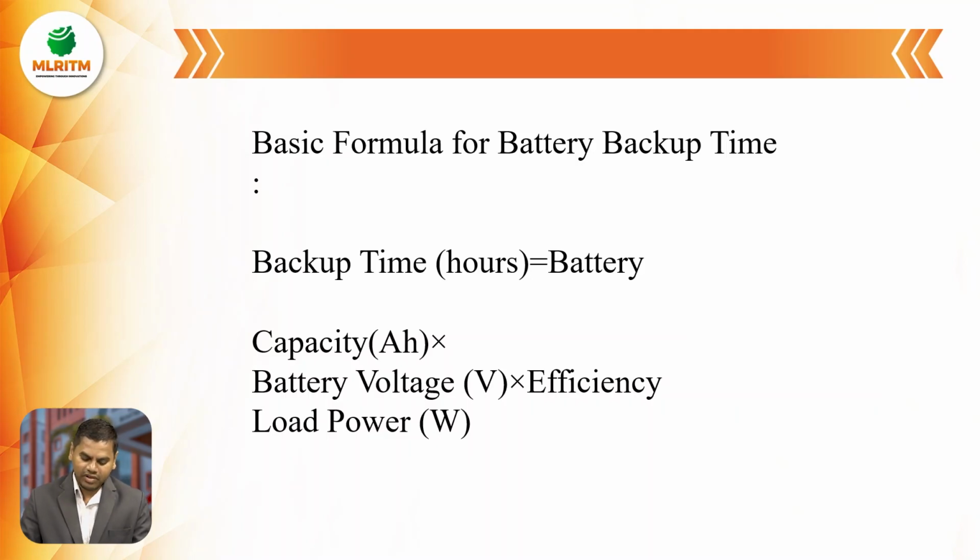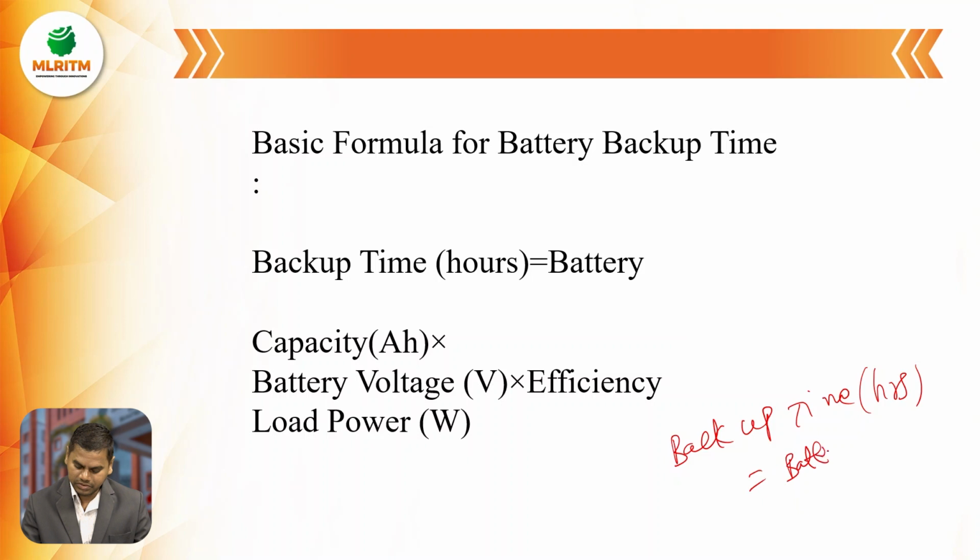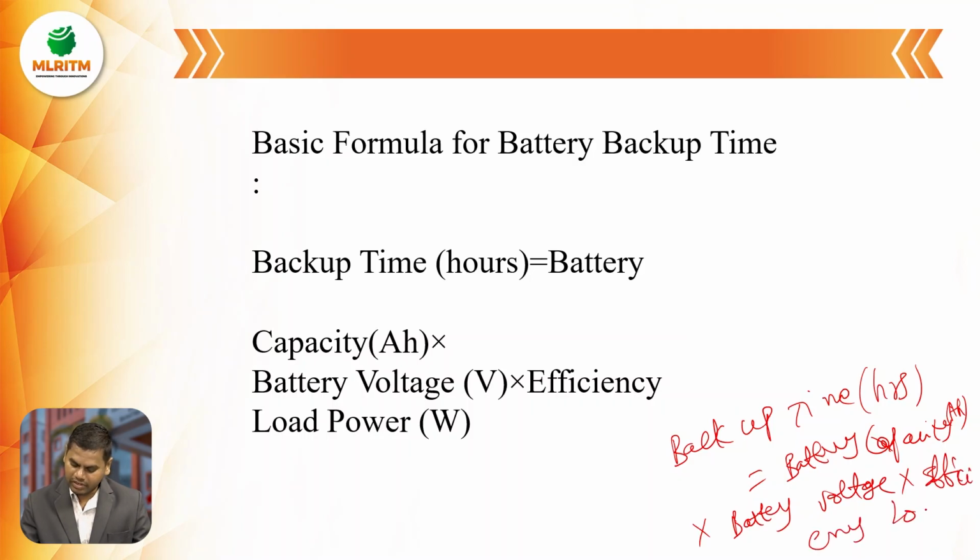So here the basic formula: backup time in hours is equal to battery capacity, which is ampere hours, into battery voltage, into efficiency, divided by load power.